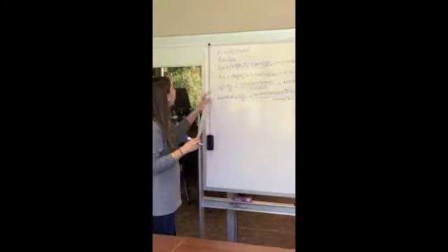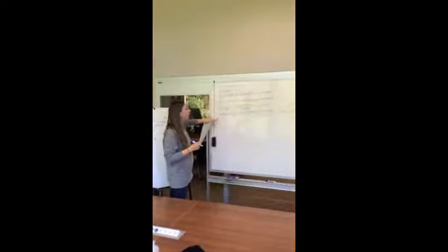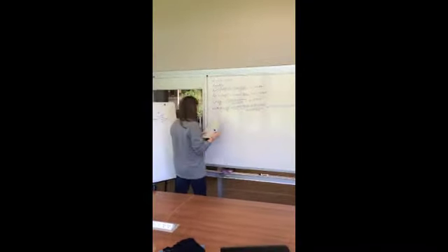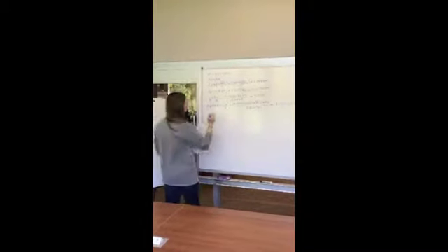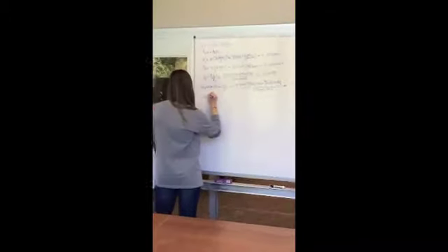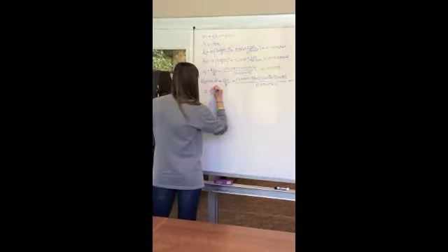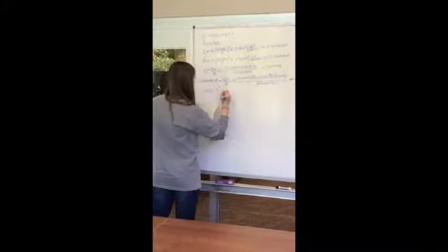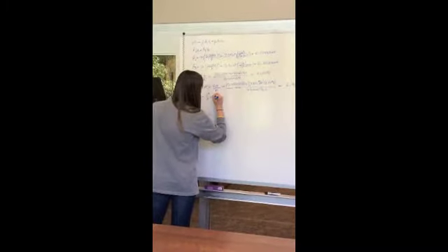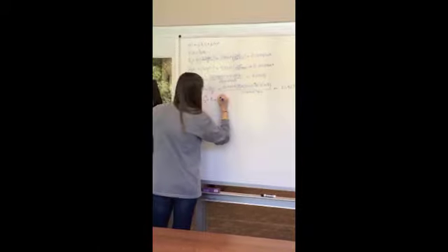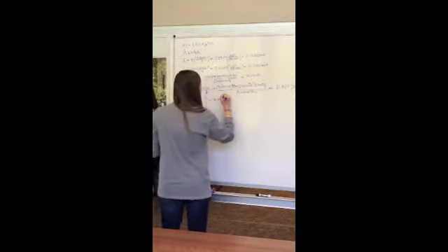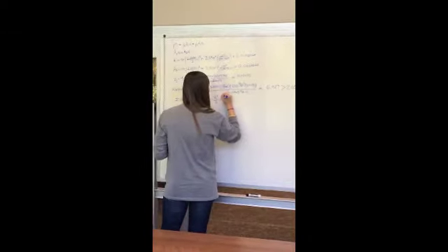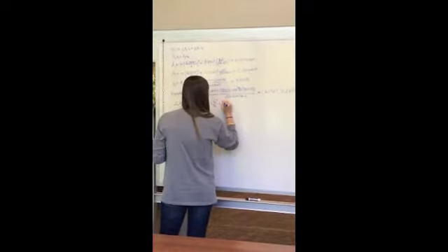So now we've found both our areas and we verified that our flow is turbulent, so therefore that allows us to use Bernoulli equation. Bernoulli equation states that Z1 times g plus V1 squared divided by 2, plus the inlet pressure divided by density is equal to Z2 g plus the outlet velocity squared divided by 2 plus the outlet pressure divided by density.